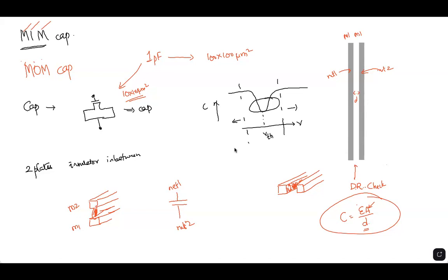You got 4 megahertz, you want to reach 5 megahertz. What are the things that you have to tweak? You cannot randomly tweak anything, right? You have to tweak the right things. For example, you look at the equation. The equation says it's GM1 by CC. CC, can you touch? You can, but there are implications. There are multiple things you may have to touch once you touch CC. GM1 looks like the simpler option. Just go ahead and increase GM1 if possible. It is possible, but how you do that is up to you.